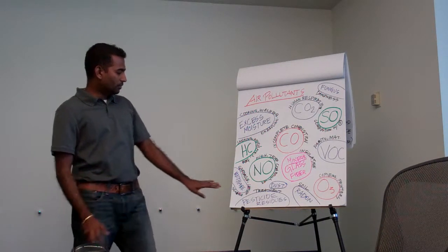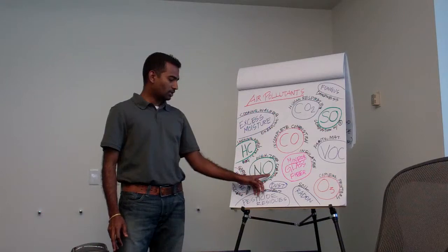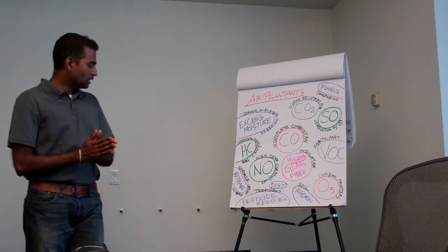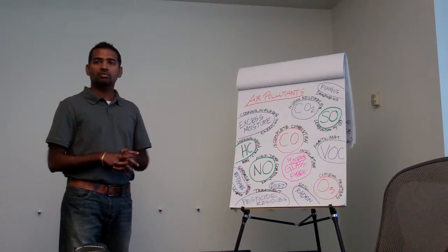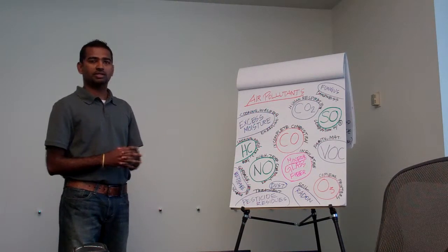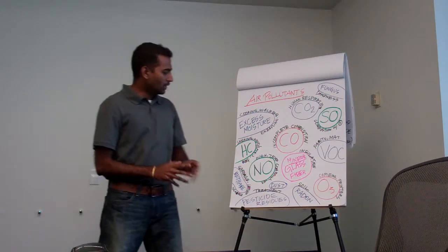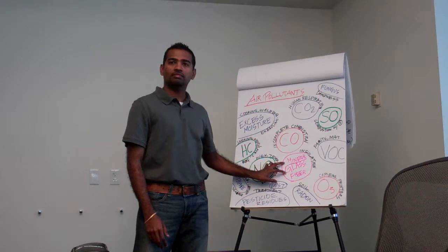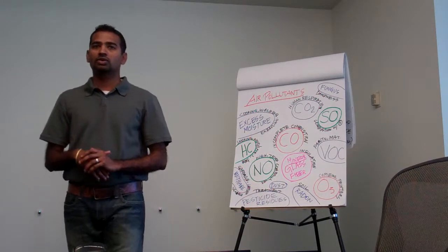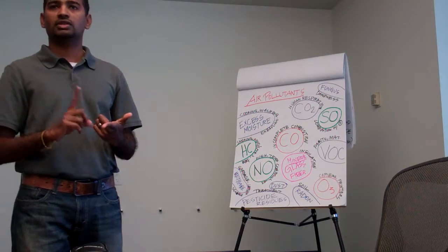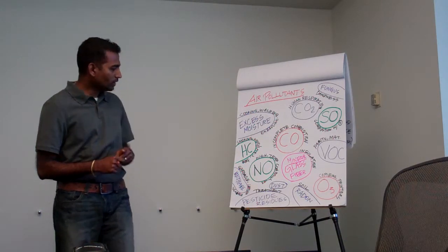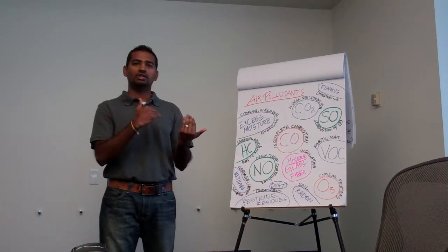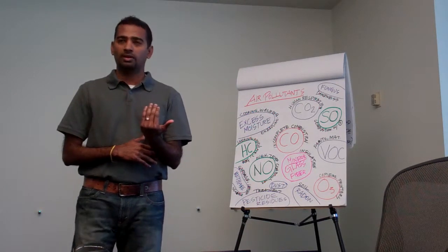And then we typically don't get into nitrous oxide because we don't have very high temperature combustion. It could be in your boiler room, potentially. Potentially, but it's mostly in industrial settings, very isolated. And then this is something that we often get into: mineral glass and fiber as an air pollutant through our insulation. We have insulation all over the place, acoustical and thermal insulation. So making sure that it doesn't get ripped and doesn't get into the airstream is very important. If it's in your plenum, make sure it's faced.